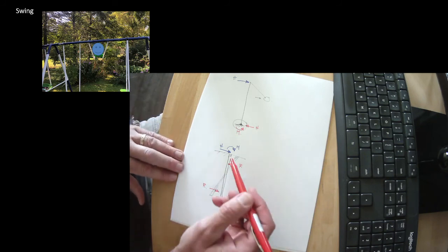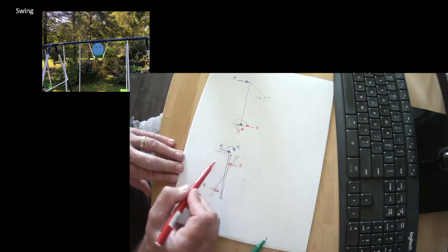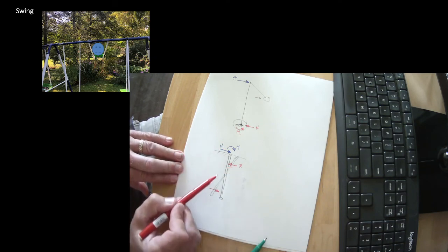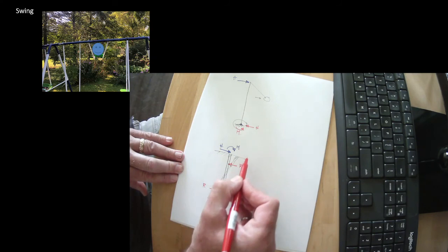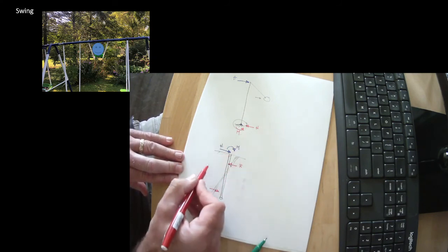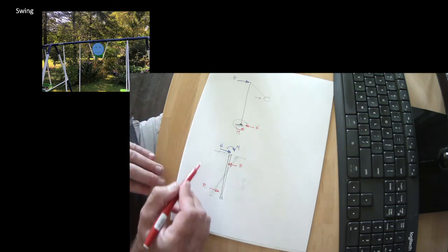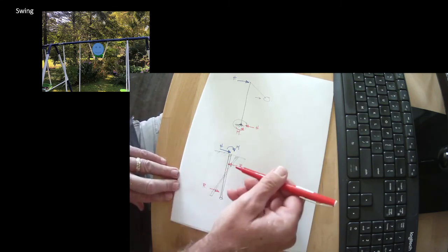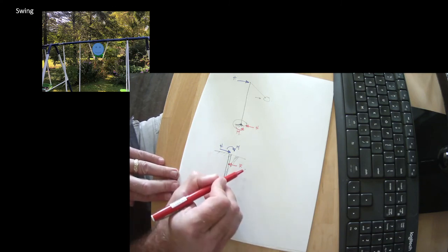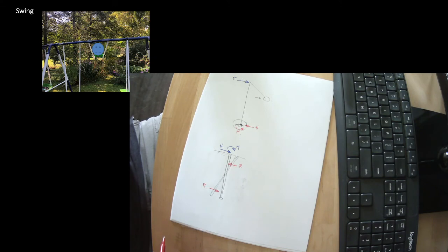Now let's look. We've got 3 horizontal forces. We know we can add them up to be 0, so that the sum of those two can be horizontal. We're applying a moment in this direction, but our reactions counter it. So we're kind of in a good place here. We know that it's going to rotate somewhere. We know that it's going to push this way on the soil at the top. It's going to push this way on the soil at the bottom.